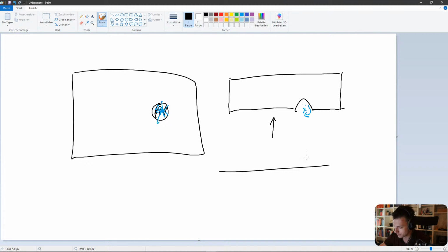You're just getting a bending moment around this axis. Symmetry constraints prevent any movement perpendicular to the symmetry plane, but a moment here will get transferred. So the correct solution is to put it in the surface center of the new nodes, even if that seems odd,